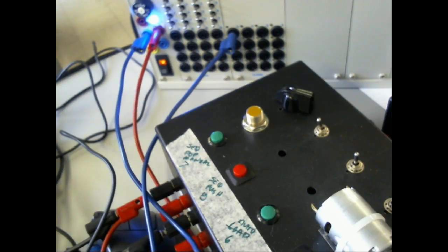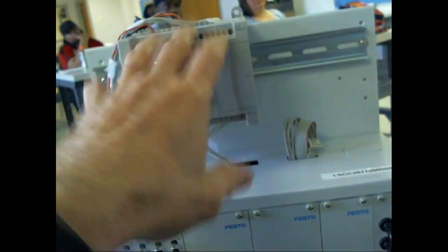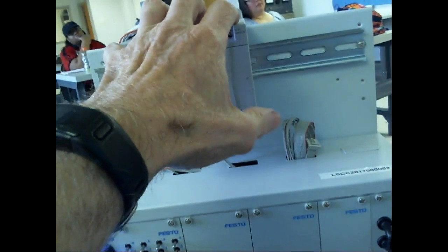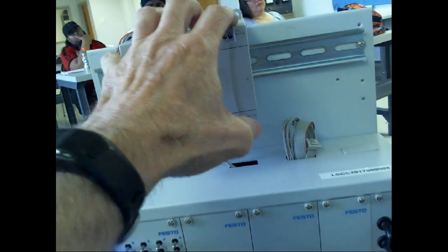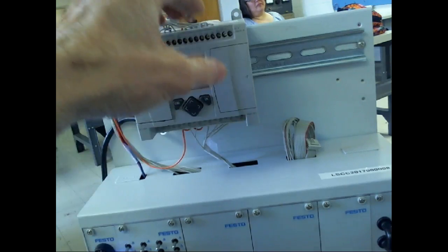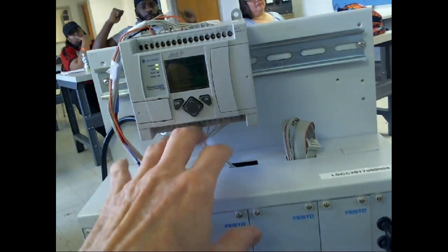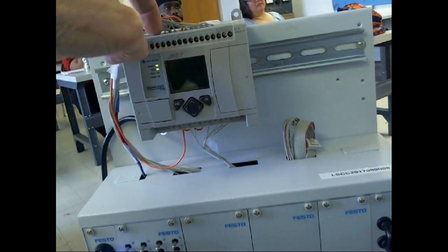Okay? That's the way you wire it. So some PLCs are set up strictly. If I was to look at the 1200, you have no option here. On the 1200s that we have, the DC/DC/DC, the inputs are set up as sinking, the outputs are set up as sourcing, but you still have a common.